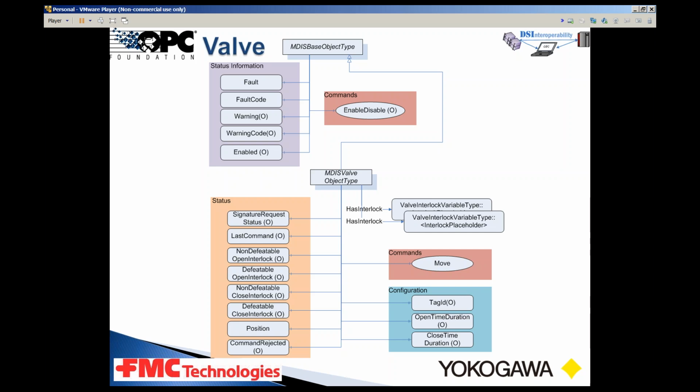And in the older systems, in particular in classic OPC or in a Modbus interface, when you wanted to make a valve move, you had to first set a number of values, double check that all those values are set to the right thing, and then tell the valve to move. And that was painful and even problematic, because if someone changed one of those settings, the valve may not do what's expected. In the OPC UA model, we added methods.